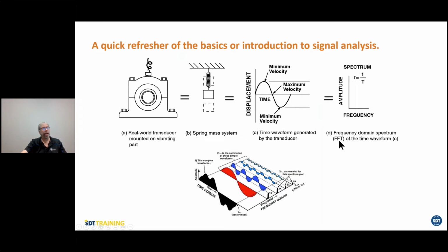We call that a fast Fourier transform, okay? And that's what 95% of vibration analysis is using, the FFT. This would be a complex time waveform over here, as you can see. As we go through the FFT process, it takes the frequencies out of it and puts them individually on the spectrum over here. Everything is a combination of problems all in one time waveform, which we break down to see what frequencies are contained within it, which tells us what's wrong with the machine.